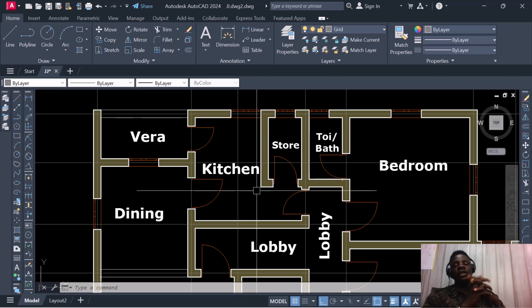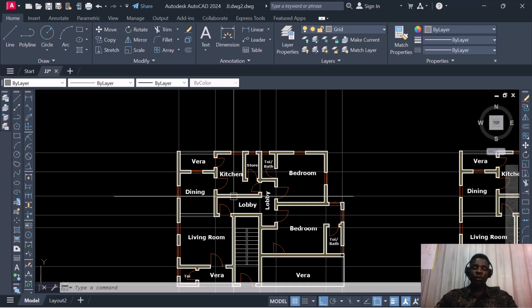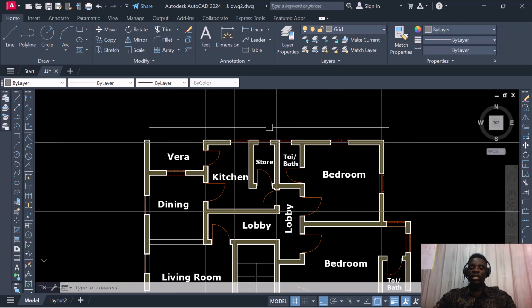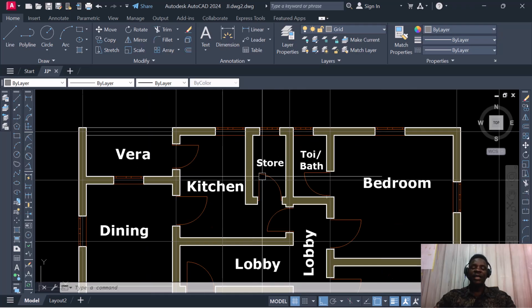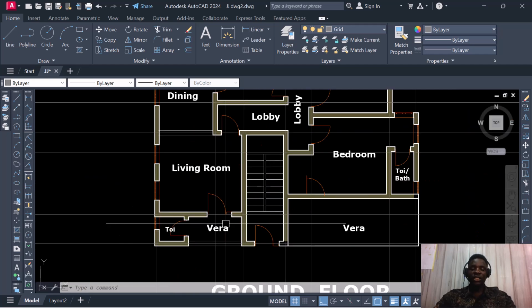In the structural drawing, there is something we call the load bearing wall and what we call the partition wall. In some situations, when you fix the structure and your structure is well supported, some walls can be considered as partition walls, while some other walls can still be considered as walls bearing load. So in this situation, this will be our basic wall where we have the grade, and this other wall here will be considered as a partition wall that separates the kitchen and the store, as regarded in the architectural drawing, right?